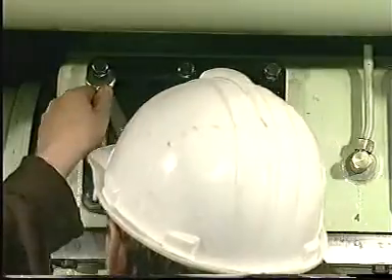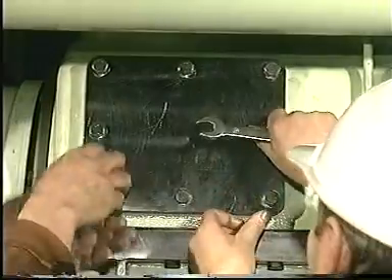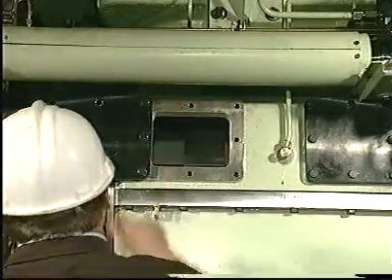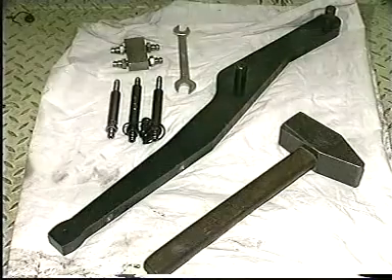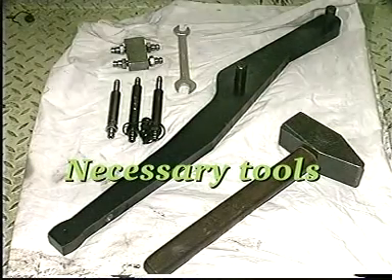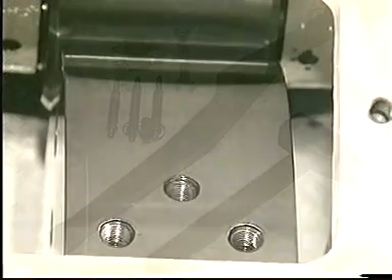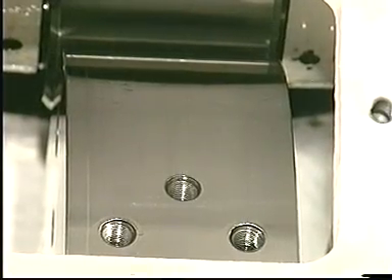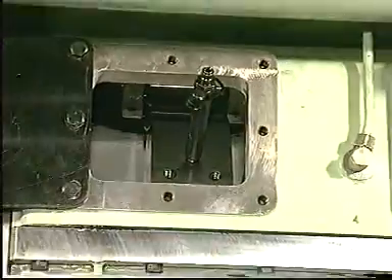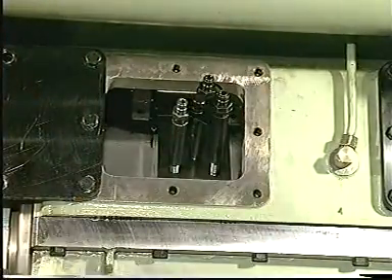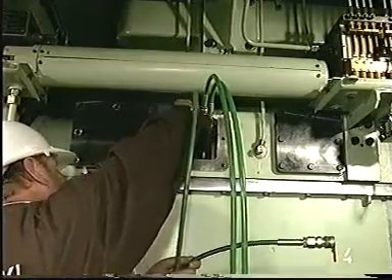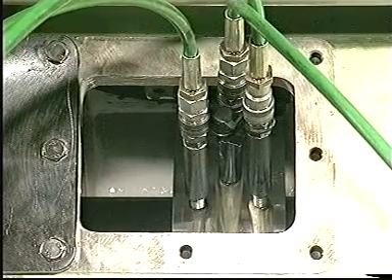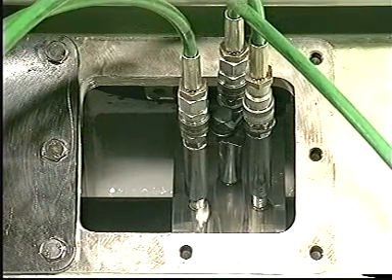Carry out fine adjustments through the small cover. If the camshaft has been dismantled or if new cams have been mounted, adjust the cams before mounting the lower part of the camshaft housing. Remove the plugs from the cam and insert copper gaskets. Mount, but do not tighten the snap-on couplings. Connect the snap-on couplings to the high-pressure pump and vent the system. When oil without air bubbles flows from the couplings, fully tighten the couplings.